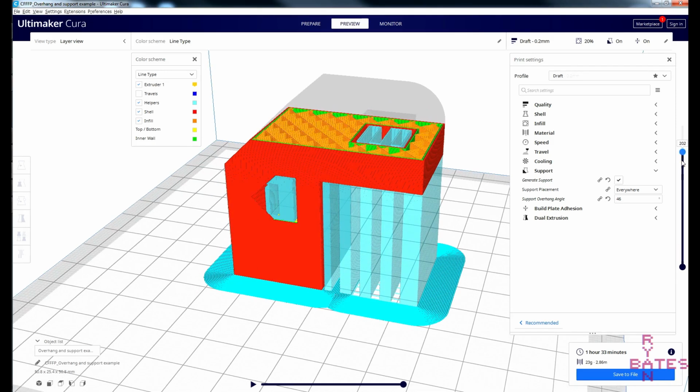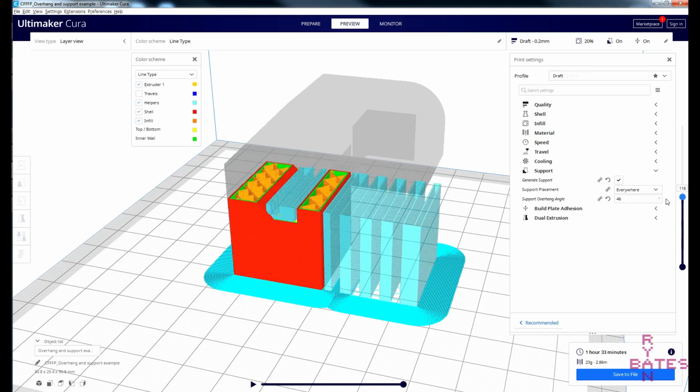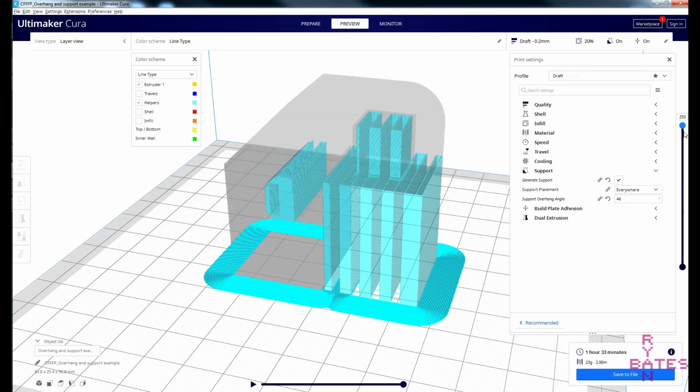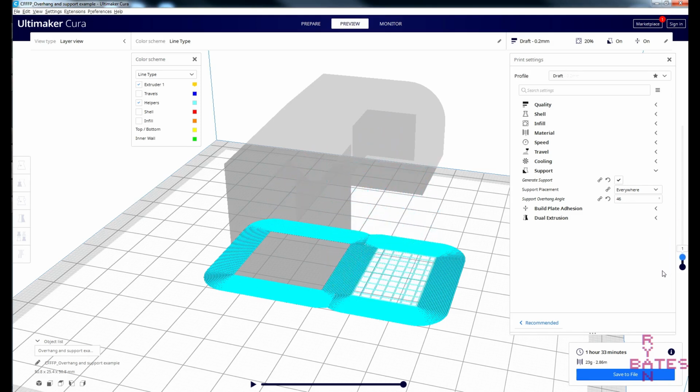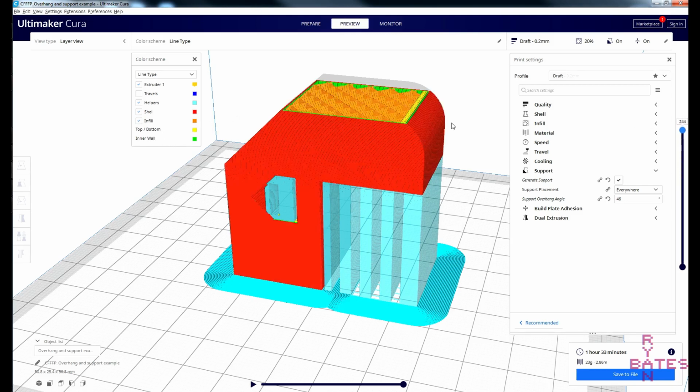The more support your part has, the more post-processing of your part might be required, essentially cleanup time. Remember, any area where supports attached to your part may leave a blemish. Thoughtful orientation is a good way to counter the need for supports. However, supports are a helpful aid when printing complex parts. Sometimes supports are necessary, and your part will be better with the inclusion of supports.